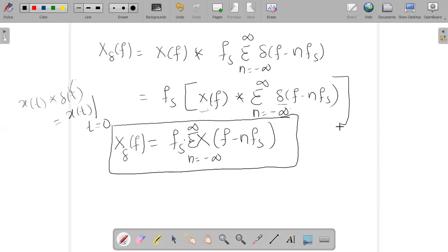So this is the expression. Equation 3 you can take, which represents the ideally sampled signal. This is nothing but the ideally sampled signal in the frequency domain, which is also a periodic spectrum. This is a periodic spectrum with the period equal to the sampling frequency, f equal to nfs. Nfs means fs, and fs is the sampling frequency. Sampling period means Ts. Sampling frequency means fs.